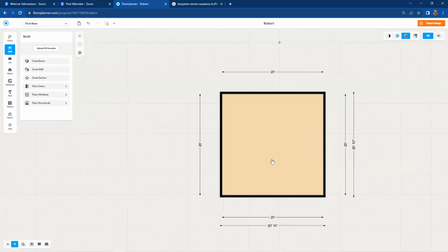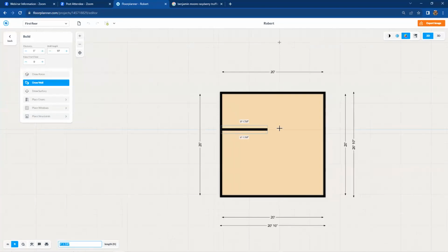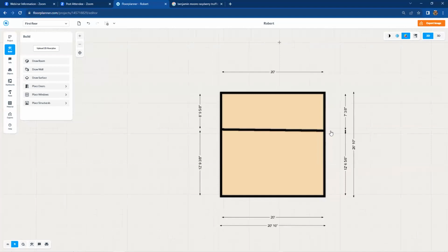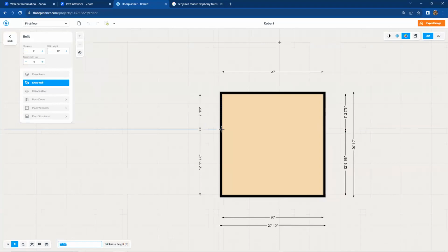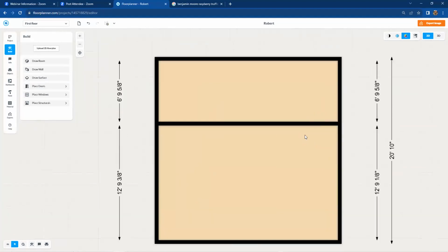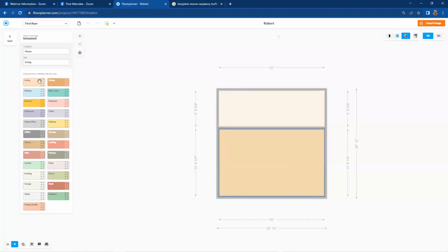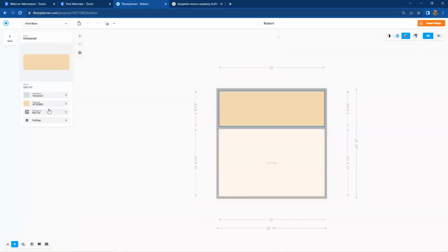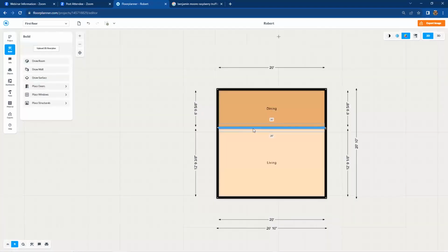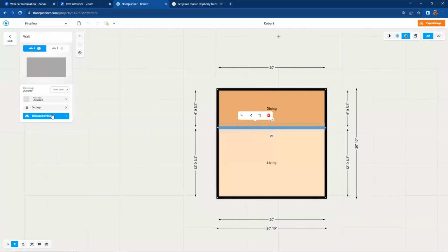Room areas, as I mentioned, open floor plans between two areas certainly can be divided by using a single wall that I showed at the very beginning. I could just draft out a wall between these two areas. Maybe it's a living room. Oops, crooked, sorry. Living room and a dining room between two areas here. There we go, straight. This room down here, I can select the area, go to its settings, unnamed, living room. I go up here and make this my dining room. Okay, living room, dining room, take that wall in the center, make it 0 thickness and settings, make it invisible.